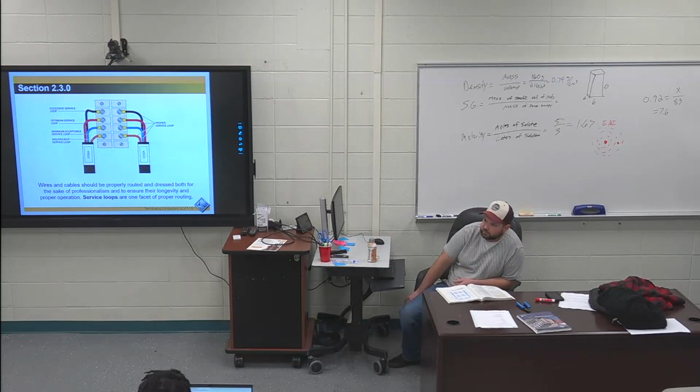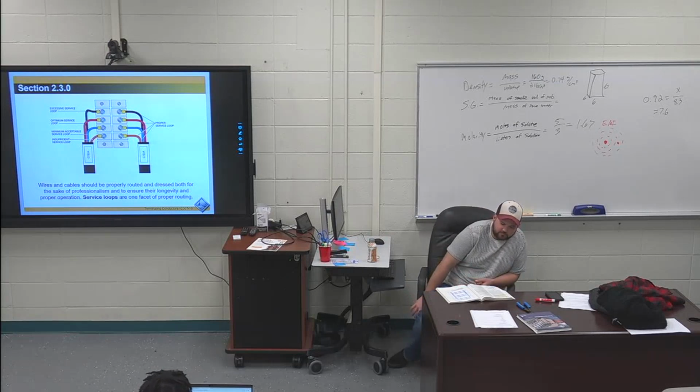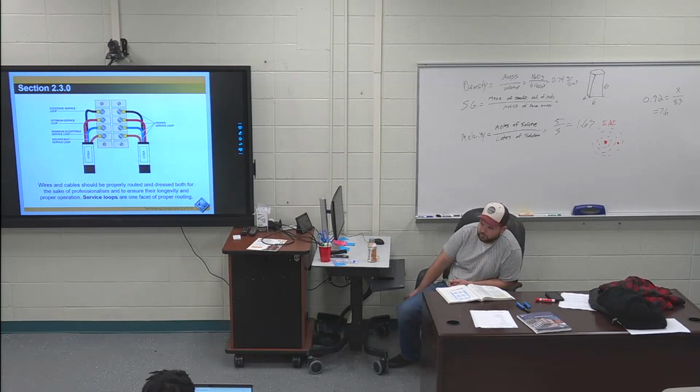And it's going to turn everything crispy or make the insulation not hold that well. The last sentence in that bullet point is also highlighted. Use grommets, chase nipples, or some other similar type of guard to protect insulation as wire passes through a metal partition. So if you're going through a metal box, make sure you have some type of grommet or something like that so your stuff's not going to rip apart on the metal.